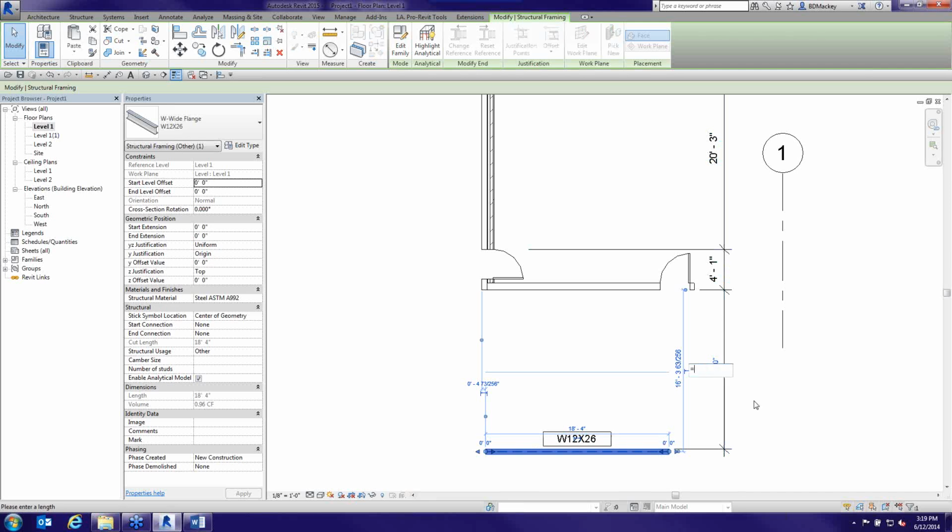I can come in here and go, actually, I wanted it 1/3 of 24 brick courses, or 39 or 42 brick courses. So I could start doing parentheses. So I could say 42 times 8 inches, and then divide all of that. That wasn't shift. Then divide all of that by 3.